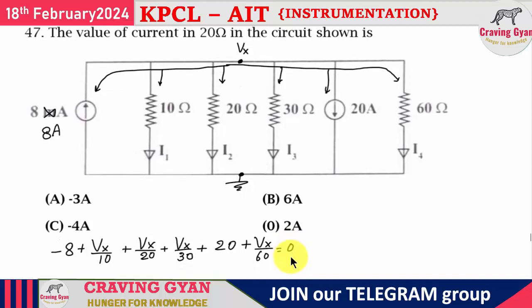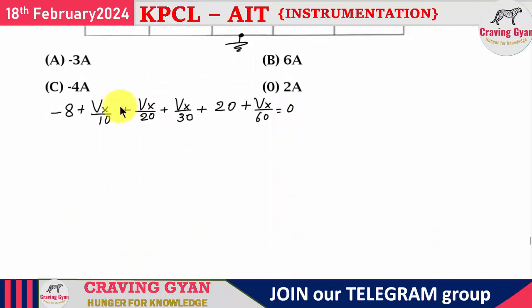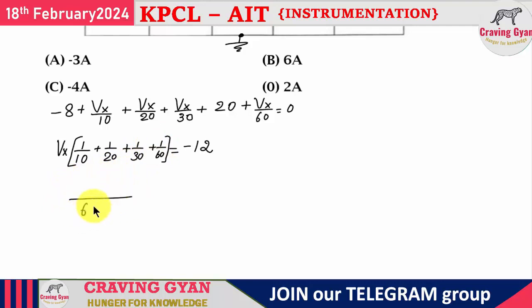Now I have written the nodal equation in order to get the value of Vx. Minus 8 plus 20 equals minus 12. Sending it to the right side, I take the Vx term common into 1 divided by 10 plus 1 divided by 20 plus 1 divided by 30 plus 1 divided by 60. 60 is the LCM for this. So Vx into 6 plus 3 plus 2 plus 1 equals minus 12. Now 6 plus 3 is 9, 9 plus 2 is 11, 11 plus 1 is 12.